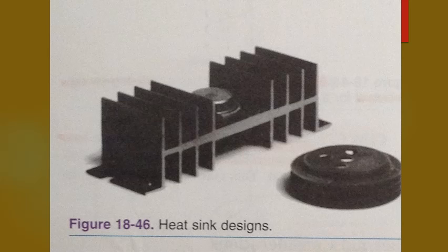Transistor precautions. Transistors are delicate electronic components. The following are a number of precautions you should take to protect transistors from damage. First, do not remove or replace transistors in circuits. When the power is on, surge currents can destroy the transistors. Number two, be very careful with close connections such as those found in miniature transistor circuits. A brief short circuit can burn out a transistor.